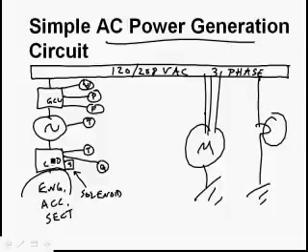So in an AC power generation circuit, we're going to have the engine accessory section driving the constant speed drive, accepting a variable RPM and spinning the AC generator at that one steady RPM it needs to spin at to deliver the right frequency. We're going to have that voltage regulator. Of course, it's going to be connected to the bus bar, and it's going to be connected to ground, and of course it's going to be connected to the field winding in the generator, and of course we're going to have all that other stuff inside of the GCU, which I'm not going to cover again.